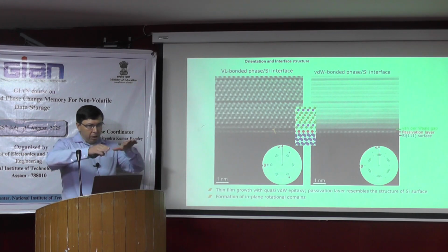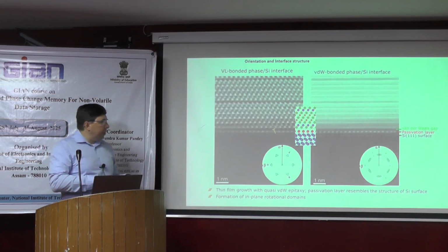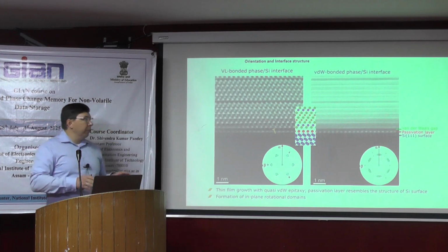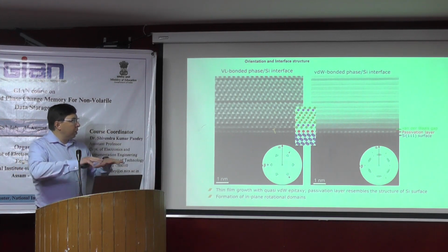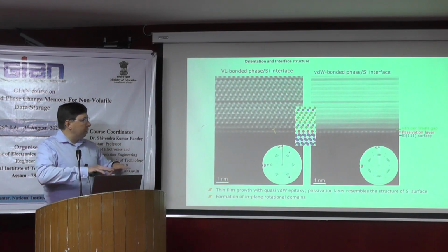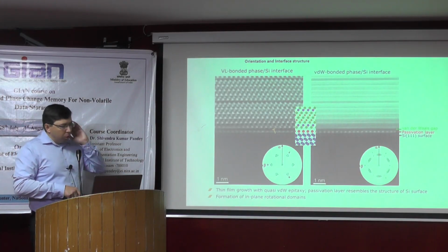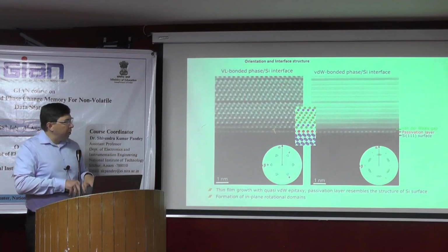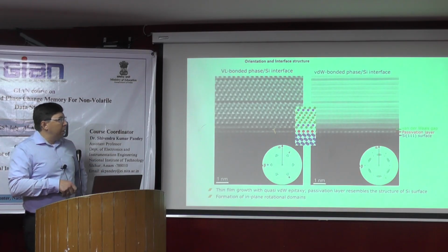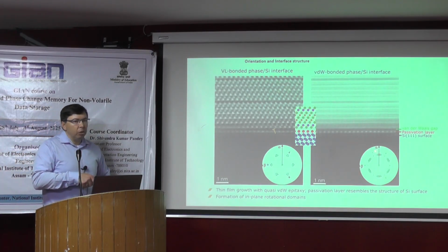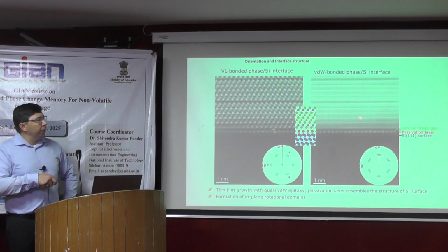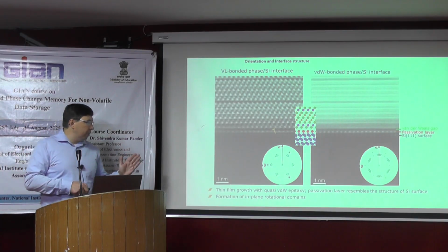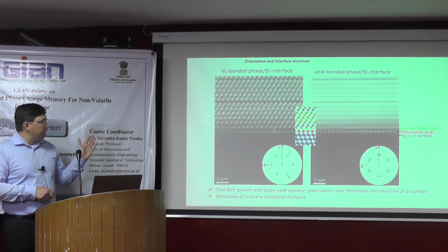So we have slightly rotated domains, and here we found these are up to 6 degrees. This is somehow also a self-organized process, and maybe also induced by strain relaxation, because we have around 10% misfit between the thin film and substrate. How to relax, how to adjust and relax this misfit?